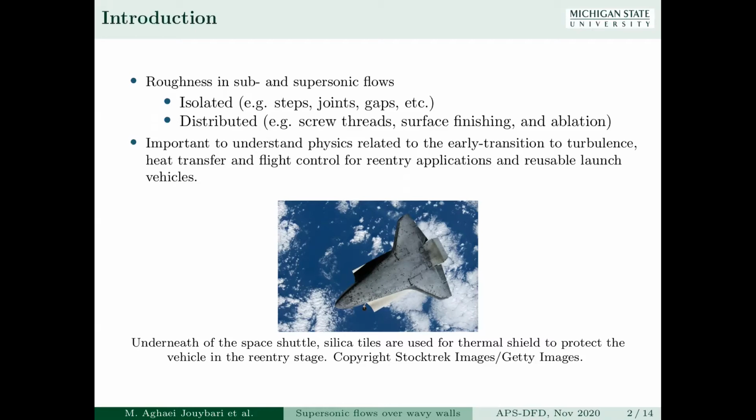For example, this figure shows the underneath of a space shuttle. As you can see, the silica tiles, which are used as thermal coatings, introduce surface roughness that can alter the aerodynamic behavior of the vehicle, especially in the re-entry region.